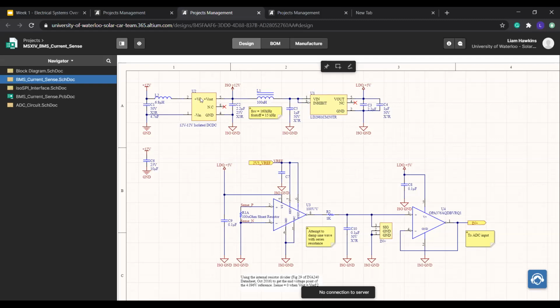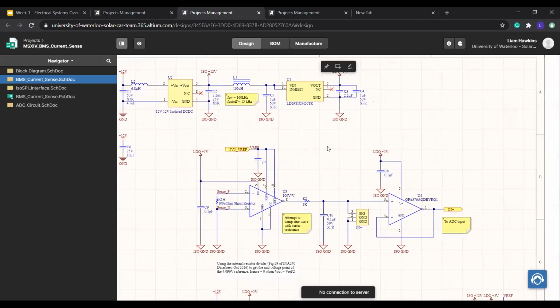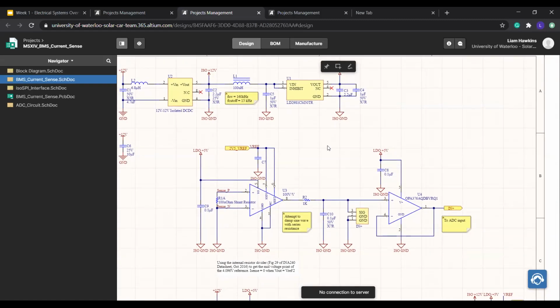Whereas in a switching regulator, it usually has inductors to store energy. And so they're much more efficient than LDOs. But because they have high switching frequencies, there's noise that's introduced to the system. So LDOs are typically used to reduce noise. And that's why we have an LDO on this board, so that our measurements are accurate and there's no noise introduced to the system.